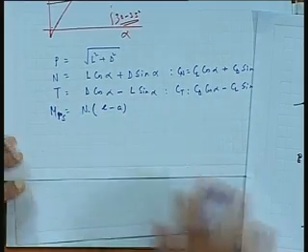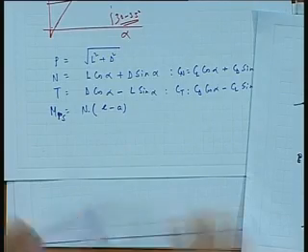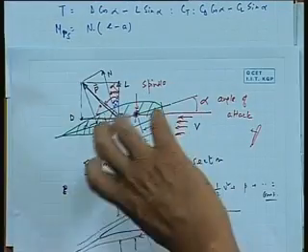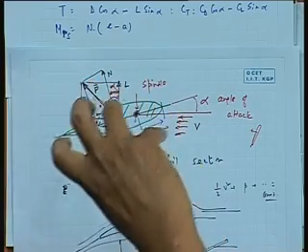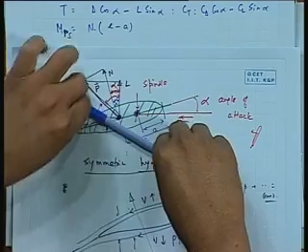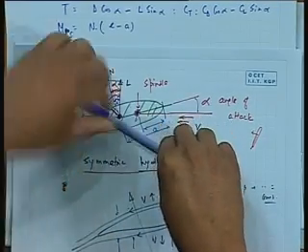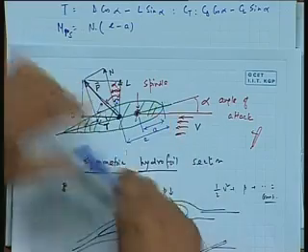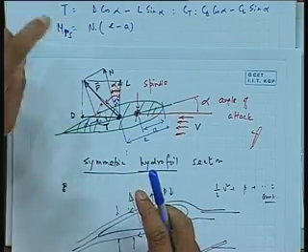This is important sometimes, because you see, you have got a rudder and they have got a steering gear machine that you have to turn. So it has to turn against that kind of moment. You are turning this rudder about this point like this, and the moment that is coming on it is so much, therefore you need to apply that much moment. So this is necessary for your steering gear design, that is why you need that.